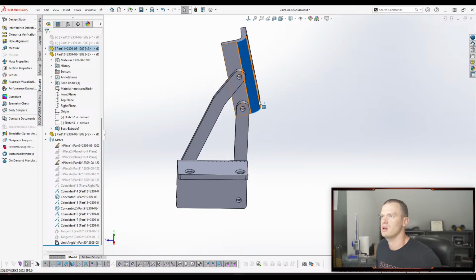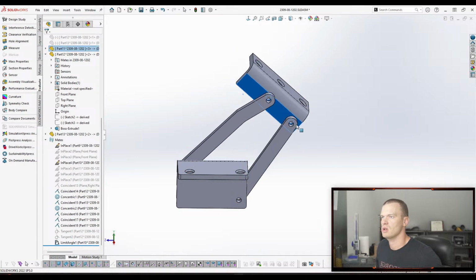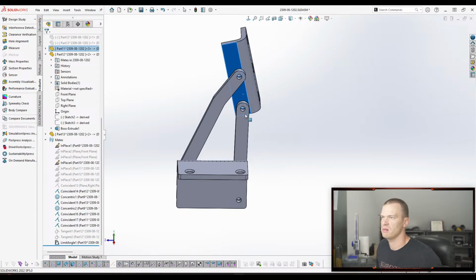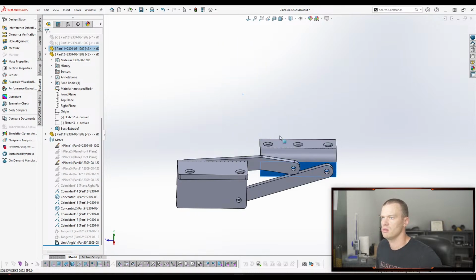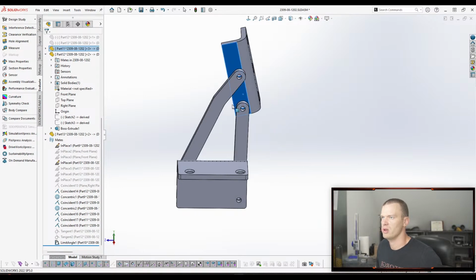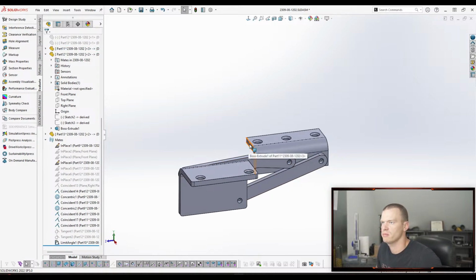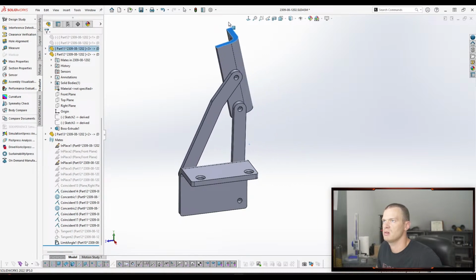Okay, so it needs to come through 78 degrees. So we'd have to pick something that, so I have to pick different faces, I think. That is one tricky part that I've always found tricky: if there's a local pass-through point, then it might not work, or I have to pick different faces to control it. So maybe this is the face that we want to control.